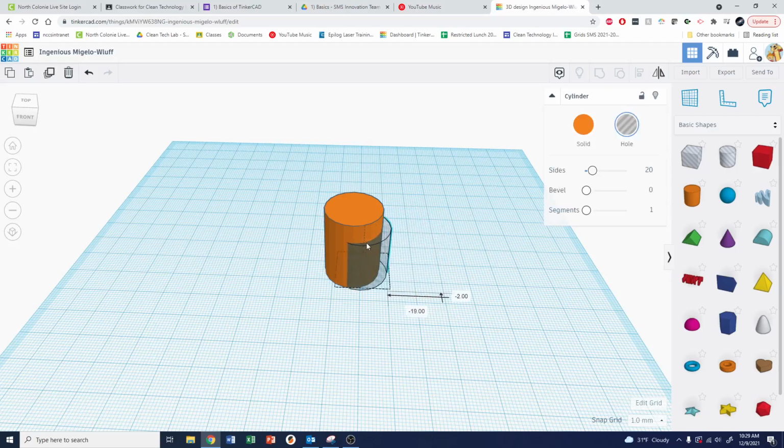So if I take this and put it somewhere around here, I can bring it up. Let's change the size so it's slightly smaller. So maybe if we click here, we'll change this to a 10 by a 10 circle. And we will change the elevation with our cone. We'll bring it up and try and place it in the center here.